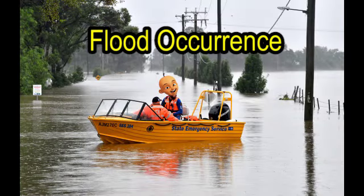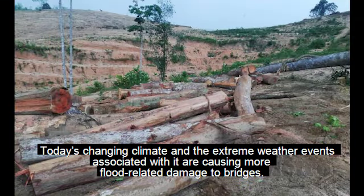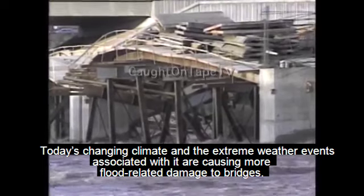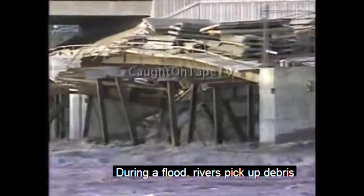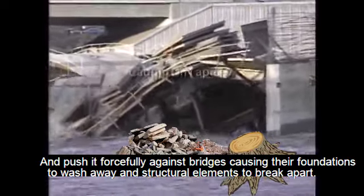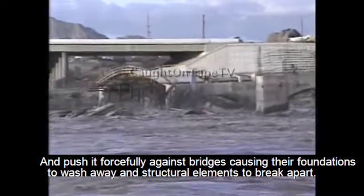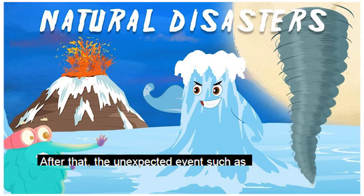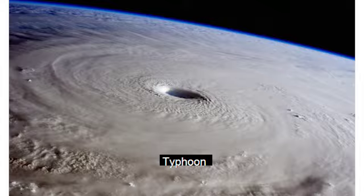Then, flood occurrence. Today's changing climate and the extreme weather events associated with it are causing more flood-related damage to bridges. Most of this damage is not from water alone. During a flood, rivers pick up debris such as trees and buildings and push it forcefully against bridges, causing their foundation to wash away and structural elements to break apart. After that, the unexpected events such as earthquakes, extreme winds, rough water and typhoons.